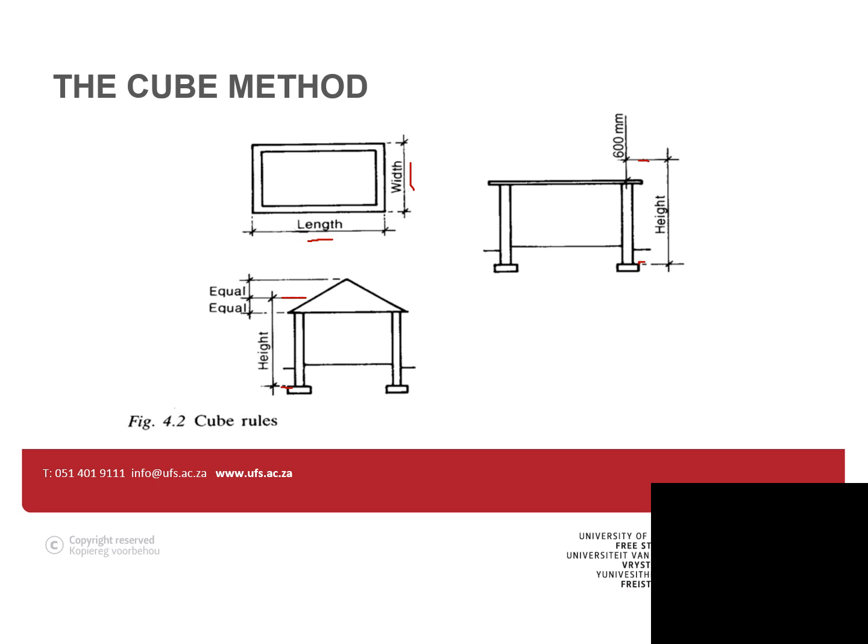So if you've got a double volume where there is no construction in a certain area, like a lobby area, you need to exclude that and maybe calculate it differently, or you need to use that lobby area cube rate only on a lobby area in your new building. So very important to break that up, and that is usually the reason why the cube method hasn't really taken hold that much as the square meter area, for instance.